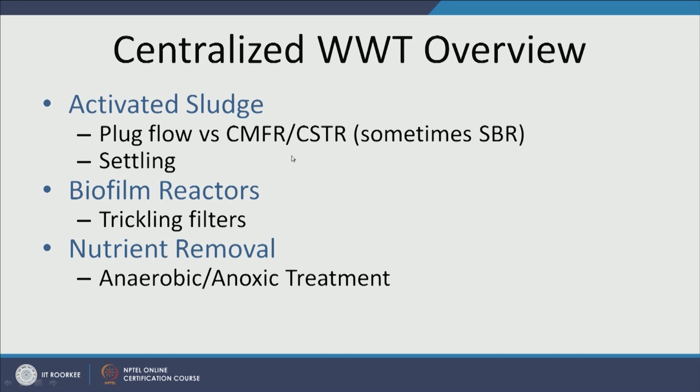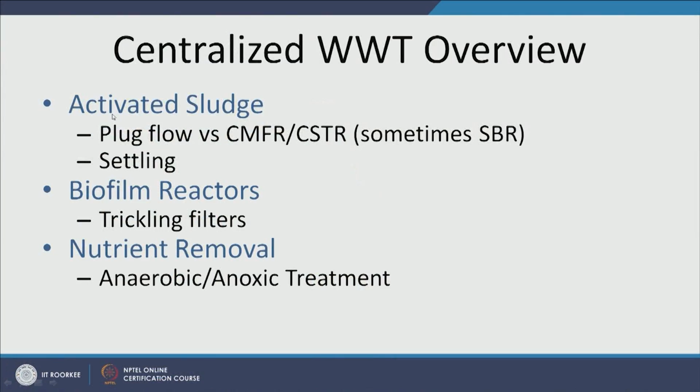If you remember, in the previous class I talked about primary treatment, secondary treatment, disinfection and disposal. In secondary treatment we use aerobic oxidation by microbes to degrade waste. So, this can be of two types, as I mentioned. Either our microbes can be freely floating in the wastewater, or they can be attached to some filter, making a biofilm on filters. The attached microbes will come under this category, biofilm reactor, and the ones in which they keep moving will come under activated sludge.